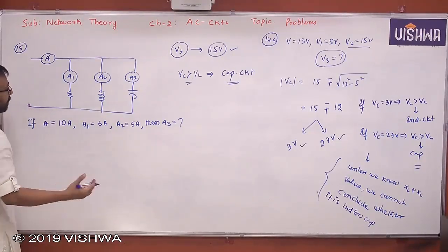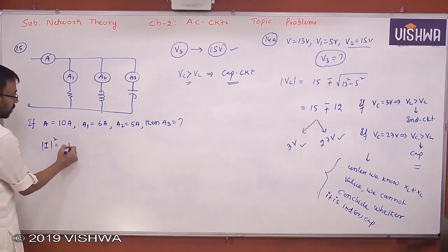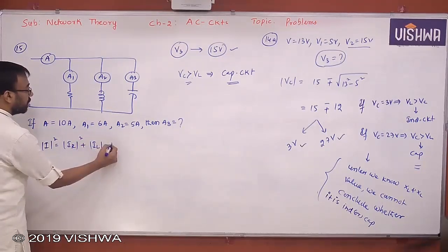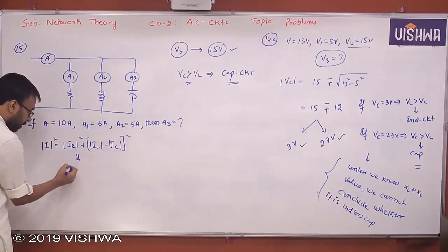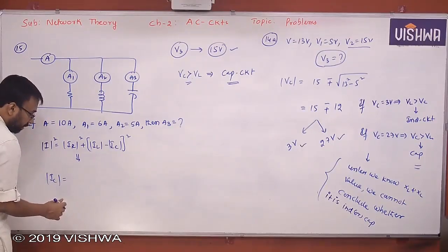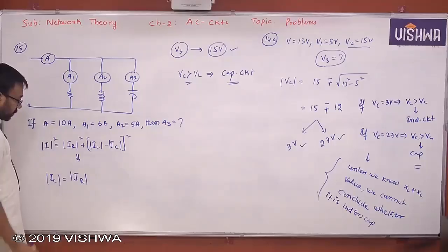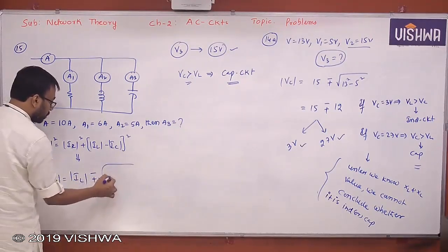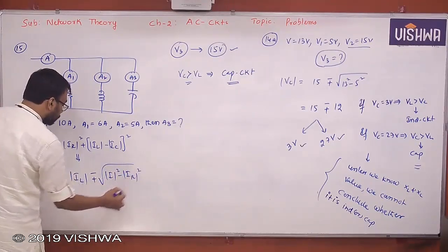Same procedure. You know that in an RLC parallel circuit you have the relation I squared is equal to IR squared plus (IL minus IC) whole squared. Yes or no? This relation you already have. Then if you take IC from this, as in the previous case we derived, what do you get here? IC is IL minus or plus root of I squared minus IR squared. Clear?